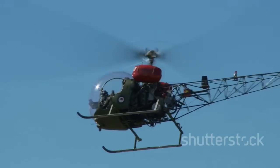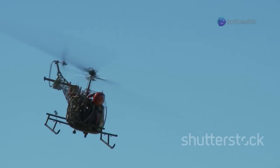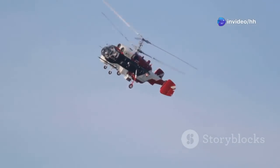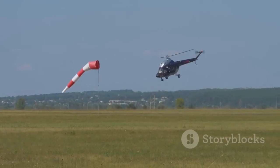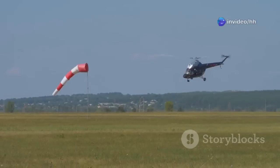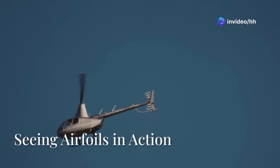This ensures a more even distribution of lift across the entire rotor disc, resulting in smoother, more stable flight. The helicopter can then perform more efficiently, with better control and less wear on the components. So, the next time you see a helicopter in flight, remember that the twist in its blades is a marvel of engineering that plays a crucial role in its performance and stability.